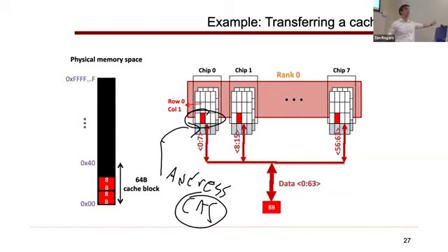So if I know I've got other cache blocks I want, I can do a RAS to another bank in that time. And who keeps track of what's in flight? The memory controller. It knows what it's asked for, it knows how long it's supposed to wait for each thing, and it makes sure that it adheres to those rules.